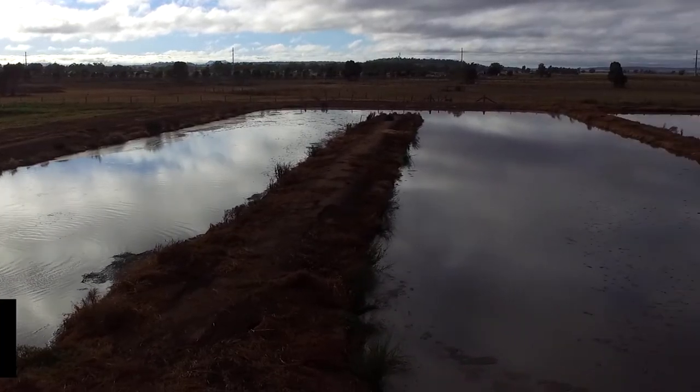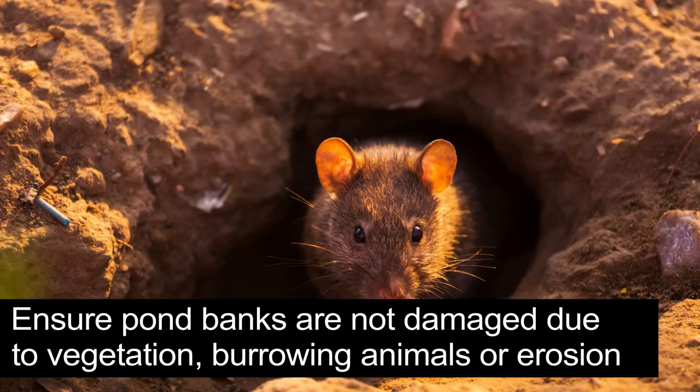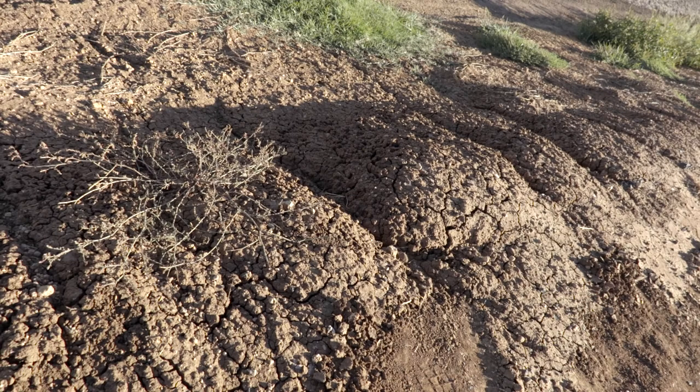Operators should also check pond walls for damage by emerging trees or shrubs that should be removed immediately, burrowing animals that should be evicted, or rain erosion. It may pay to apply protective biodegradable matting which allows grass growth and protects from erosion.